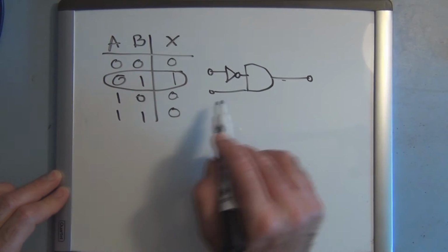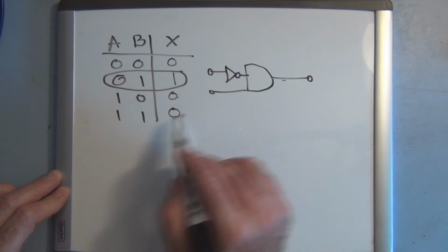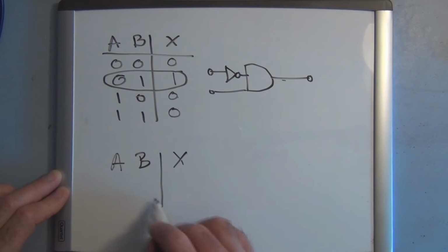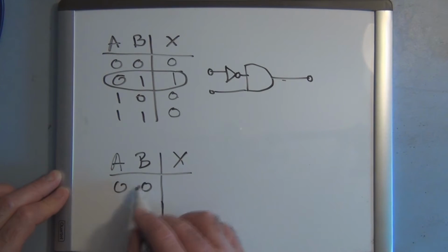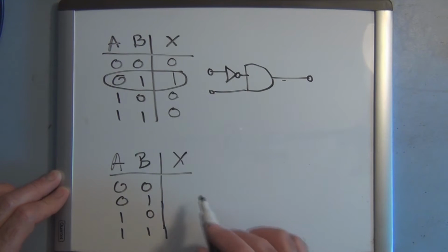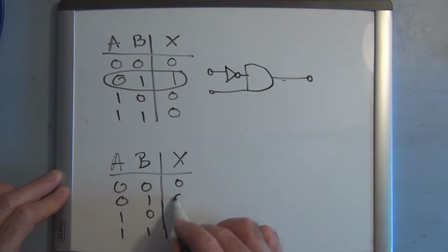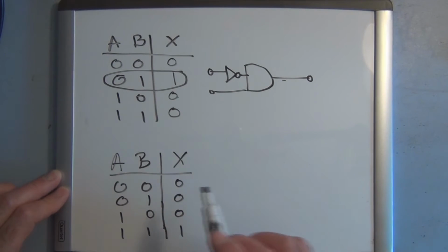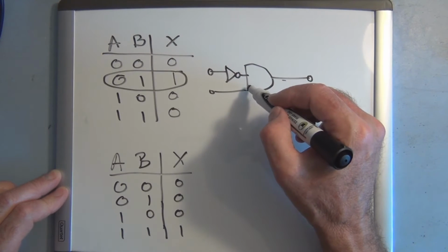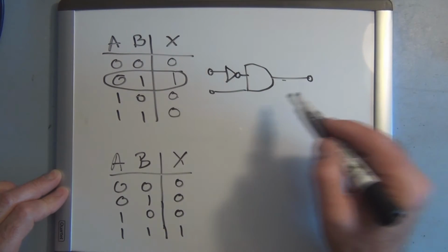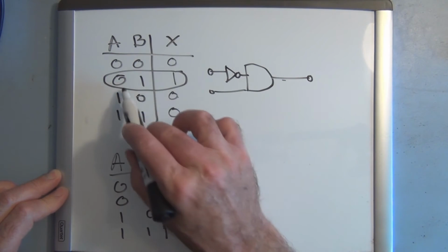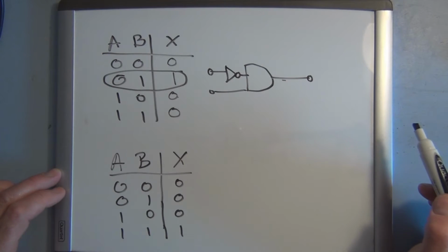An AND gate is defined so that the output is high when both inputs are high and is 0 for all other cases. So all we have to do is guarantee that there are two highs on the input of the AND gate, and we do that by placing an inverter where the variable is 0.